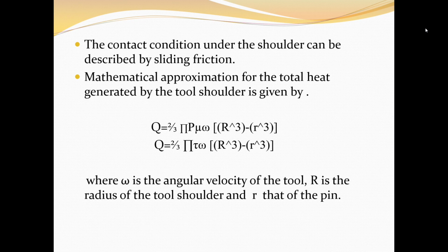The major difficulty in applying these equations is determining suitable values for the friction coefficient or the interfacial shear stress. The conditions under the tool are both extreme and very difficult to measure. To date, these parameters have been used as fitting parameters, where the model works back from measured thermal data to obtain the responsible simulated thermal field. While this approach is useful for creating process models to predict, for example, residual stresses, it is less useful for providing insights into the process itself.